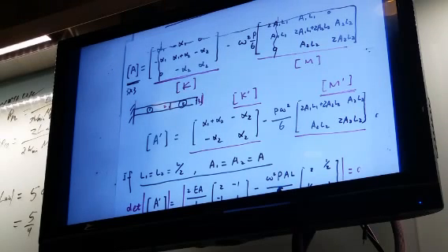Just imagine I discretize this structure into 10 bar elements. You will get 10 different frequencies. And the difference between those frequencies may not be that huge because you just put more mesh into the structure, but the numbers will be different. So everybody should be getting a different frequency. If you get exactly the same frequency as another student, that means you just copied their mesh. So that will not be cheap.